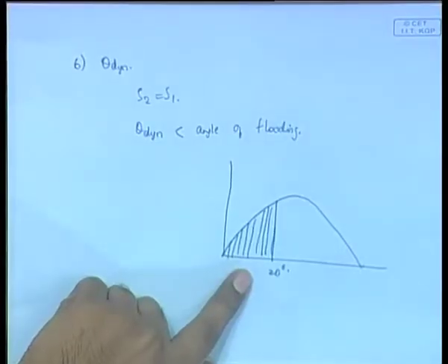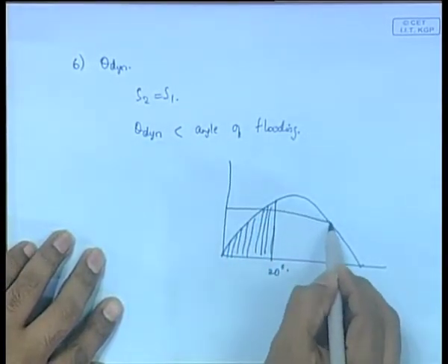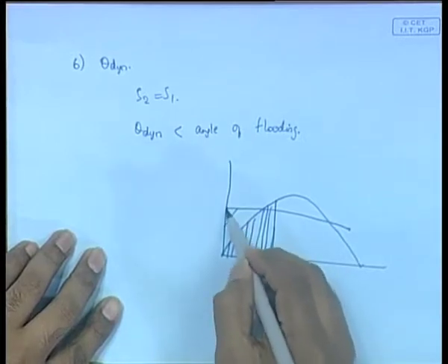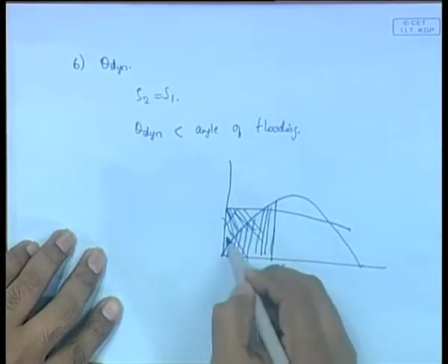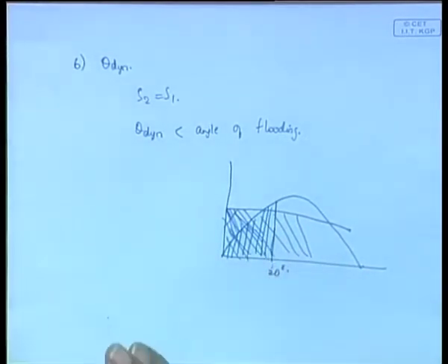So it keeps going. The work done by the righting moment is given by the area under this curve. I think it should be clear. Now, on this we sometimes draw a heeling arm. The area under this curve, up to 20 degrees, will give the energy given by the wind to the ship for heeling it. So the first one is the energy given by the wind to the ship, and the other is the work done by the ship in resisting that, which is like saying the energy taken out of the ship.